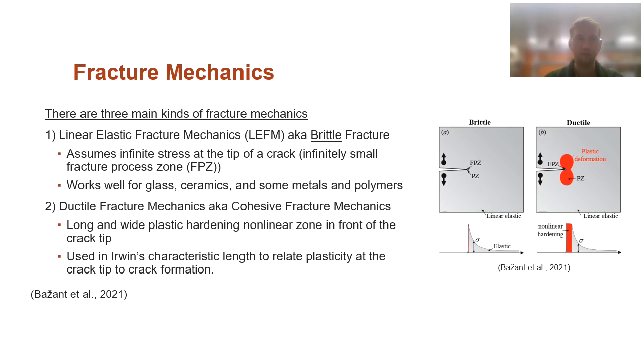Really quickly, we have three kinds of fracture mechanics. The first being linear elastic fracture mechanics, LEFM. LEFM applies to brittle materials, things like glass. Think of glass. That's probably the best explanation for it. And if we look at the diagram on the right, I think this really puts everything in perspective. We can see the FPZ there, the fracture process zone, and the PZ, the plastic zone, for brittle materials are all very small. Now that's important for LEFM because we're assuming infinite stress at that crack tip.